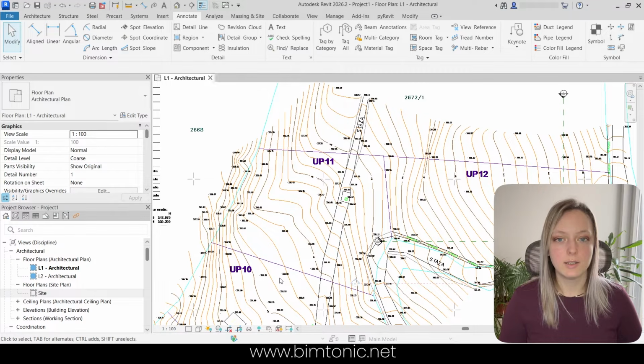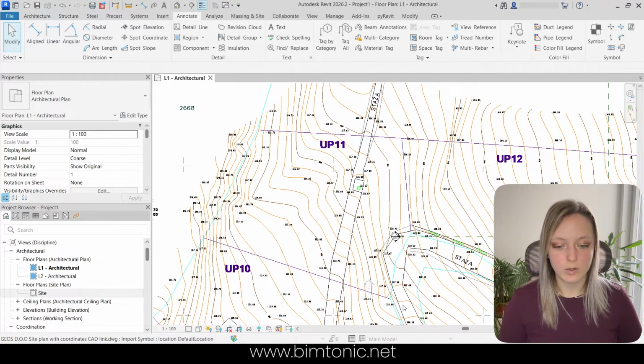And when we are setting the project north in a project, we basically use one of the sides of the plot. It is something that we set up right in the beginning, and that is basically the orientation of our floor plans and our building. And I'm just going to use this purple line to be the orientation of my project north. And this is something you usually do when you begin working on your project, like right in the concept stage. Basically, you choose some road or some side and set up your building according to that. I am in this case going to be using this purple line, and I'm going to set up my building and my project north to be parallel to this line.